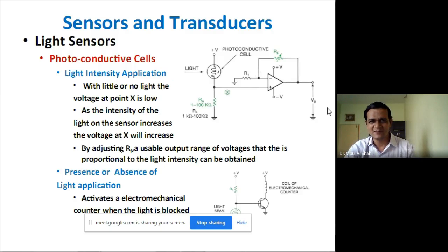So that will become our complete closed loop arrangement, and we can have a feedback from our microcontroller based system so as to monitor and maintain this light source as per requirement. So we can change this light source as per its angle, its location, and we can monitor and maintain this temperature with reference to this change in the voltage. So this voltage is analog voltage. Further, we can process that with reference to the analog to digital converter.